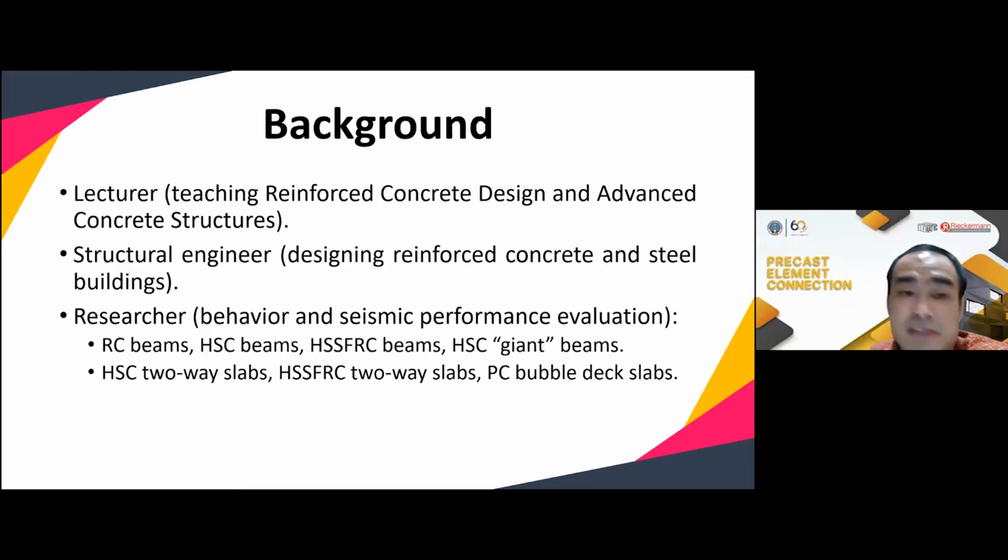Shear is a very brittle failure. So the failure was very sudden and we can see the slab fail, making circular cracks around us. We are standing at the top of the column support, so we are safe. It was a very interesting experience for me because it's the first time we tested this punching shear for